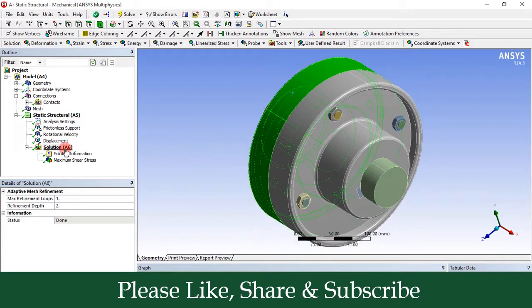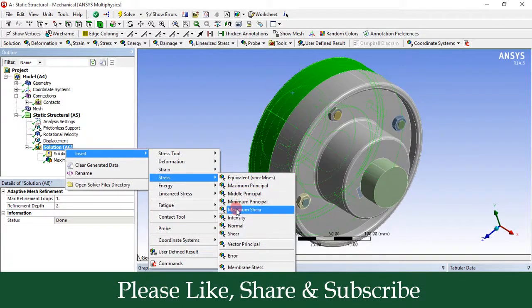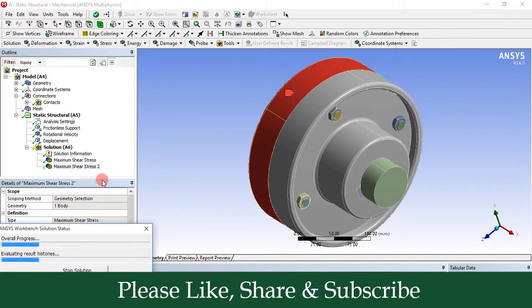Now left click on this solution, then right click on this solution, go to the insert, go to the stress and select the maximum shear stress parameter. Now we have applied the maximum shear stress parameter for only input flange. Now we have to solve this. So right click on this and click on evaluate all results.